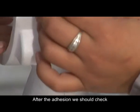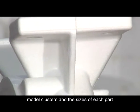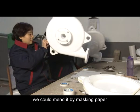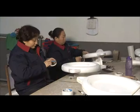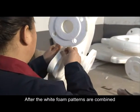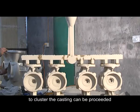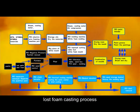After the adhesion, we should check the adhesion joints, the surface of the model clusters, and the sizes of each part. If it needs to be mended, we could mend it with masking paper. If one side is glue-cohesive, the other side could be coated well. After the white foam patterns are combined into a cluster, the casting can proceed, which is the so-called black area of the lost foam casting process.